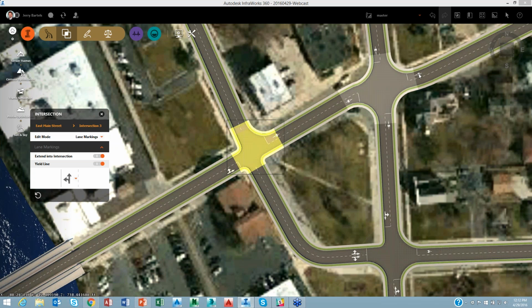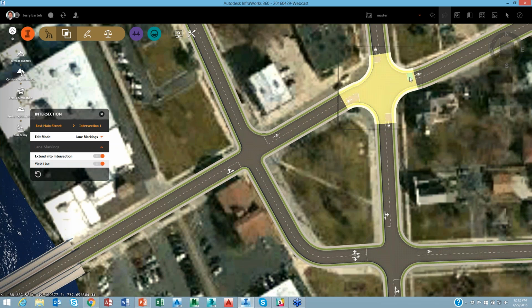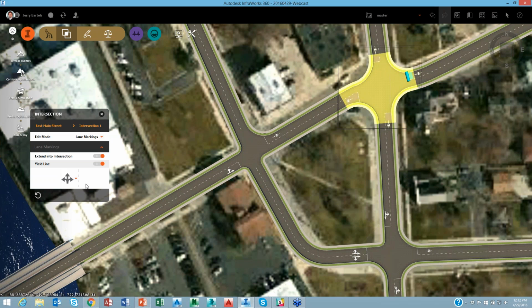So does this one. Now this one, if you remember from the graphic, was one way. It only went from west to east. I could change this to a one-way street as well. However, we're going to look at a roundabout, and one of the limitations with the roundabout geometry right now is I can't have a leg that's one way, but that's okay. We will just reduce the amount of traffic flow that we would have in this area, and when we assign the vehicles to it, we will just not have any vehicles coming from that direction.